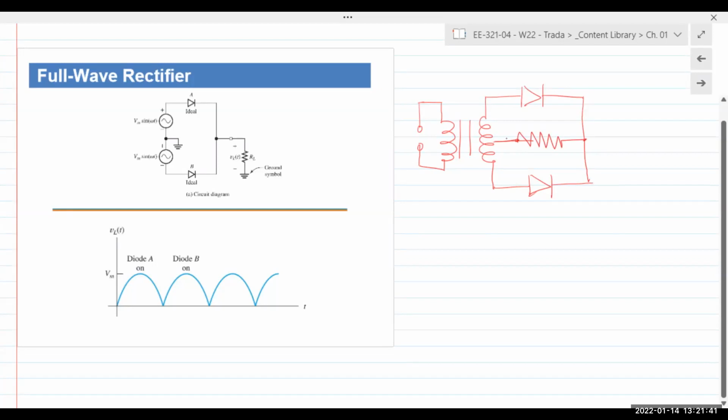When the diagram shows a dual power supply, in real life it's not going to be like that. You're not going to have two actual separate power supplies coming in. It's basically one unit, like the transformer. But somewhere in the secondary coil, there's a wire coming out, and we call it a center tapped transformer. So this circuit is known as a center tapped full wave rectifier.